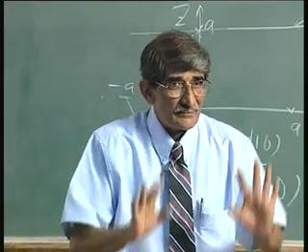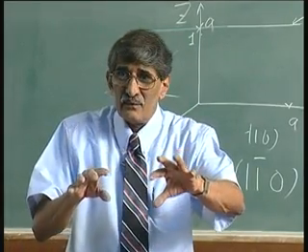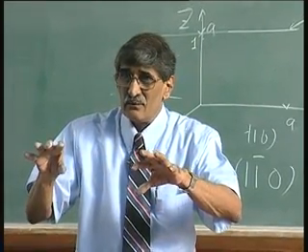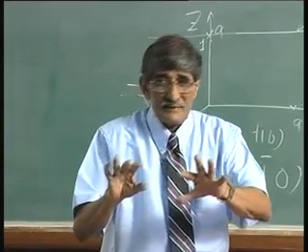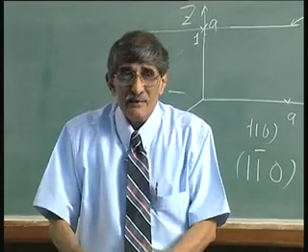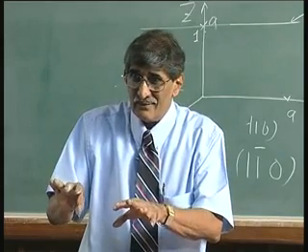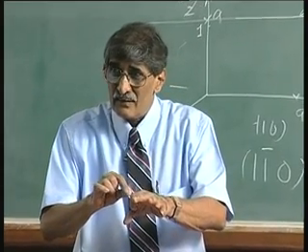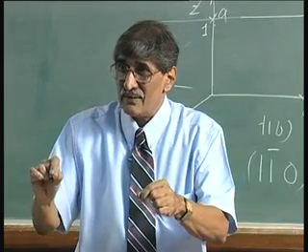This is a neutral plane. Even if there is some charge, in fact, because gallium has 3 and arsenic has 5 electrons, there is some ionicity. The bonding is not perfectly neutral like in silicon. There is some shift of electrons towards arsenic actually. So gallium will be slightly positively charged, in fact plus half, and arsenic will be minus half charge.